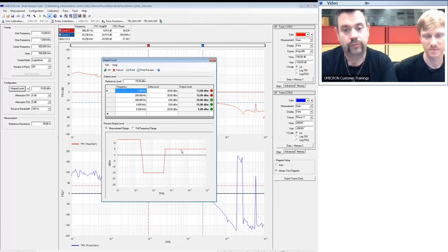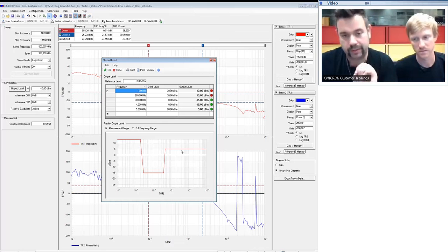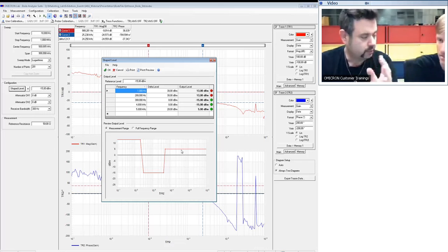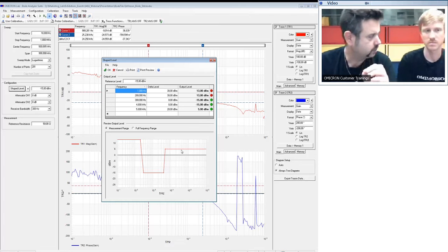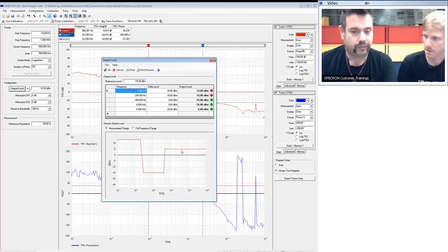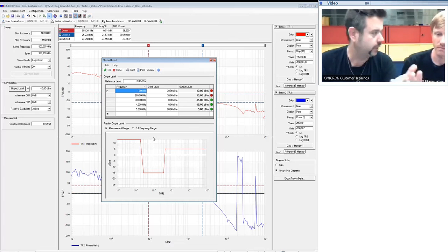How to do this? First, you have a look at the phase margin and adjust the level until you have the perfect phase margin. You remember this level. Then you go to the other point for the amplitude margin, the gain margin, and again you adjust the level. If the point is no longer moving, you know the perfect point for this signal, because you also should not have any noise in that area. Then I found out it's 5 dBm and minus 15 dBm, and I programmed these two levels first. After that, I wanted to get rid of the noise at the low frequencies, so I increased just the low frequencies, and that's how I got a nice curve.